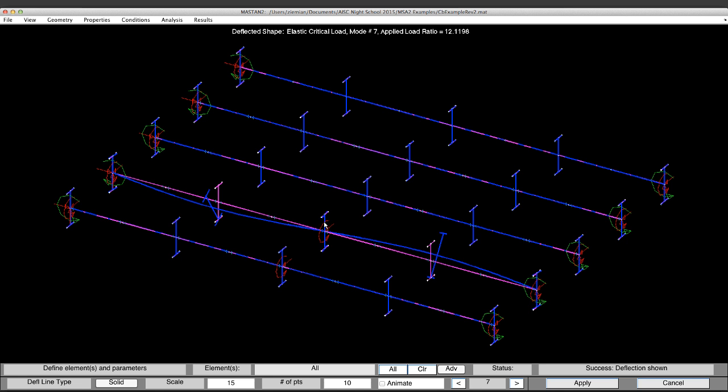Again, the middle of the beam is braced from twist, so it can't rotate. And what we basically got is 2 beams buckling. But it is a continuous beam. All right. The load factor there was 12.1, so it's taking about 12,100 kips to buckle this thing.